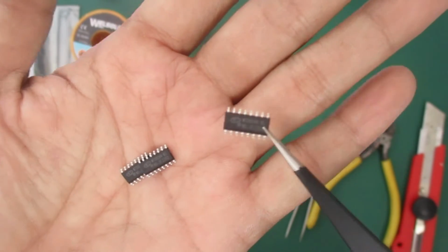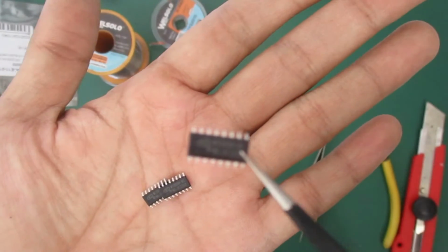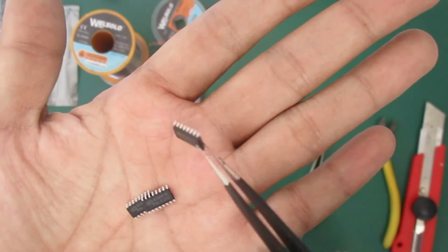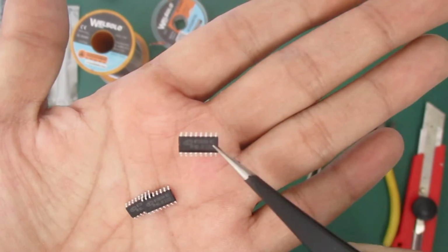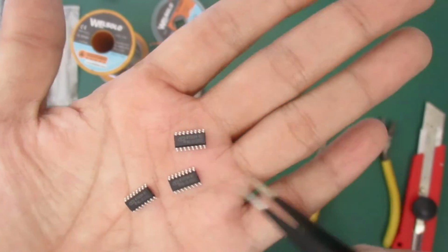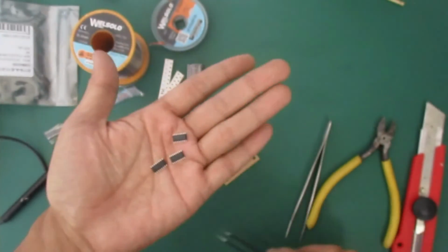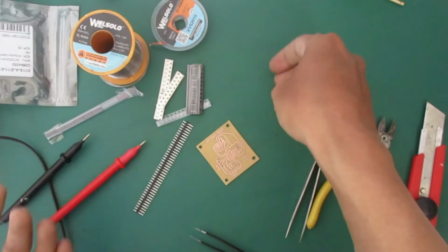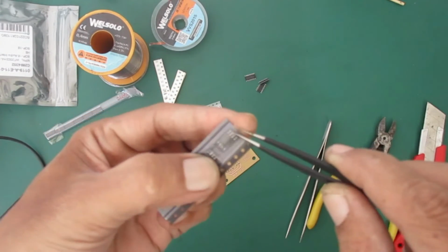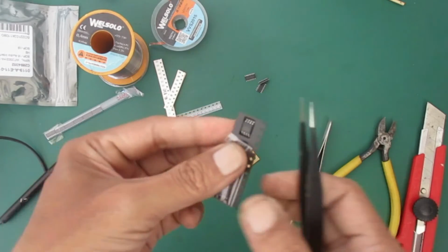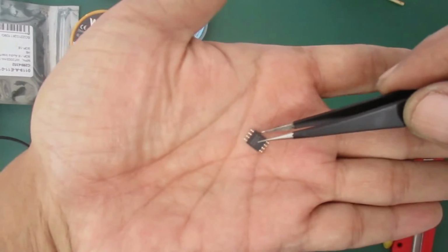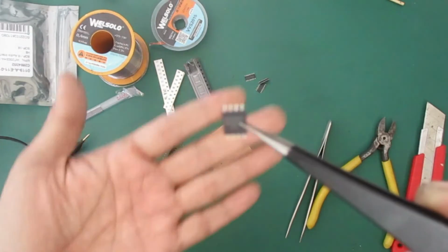This IC packaging is SOP16. As long as you like soldering, I'm sure this component is very easy for us to solder by hand. For MP3 file storage, here we will use SPI-Flash Winbond W25Q16. Of course, you can use a memory IC with a larger capacity.